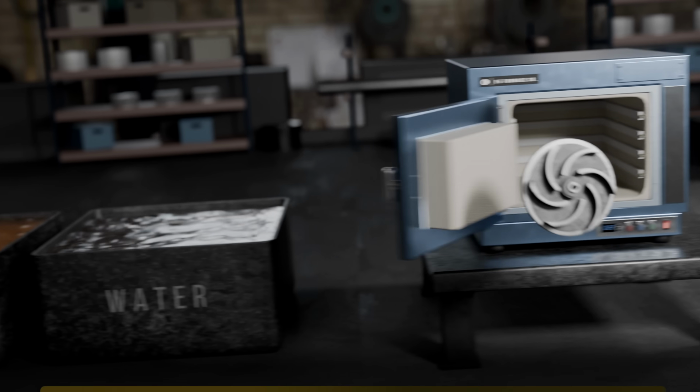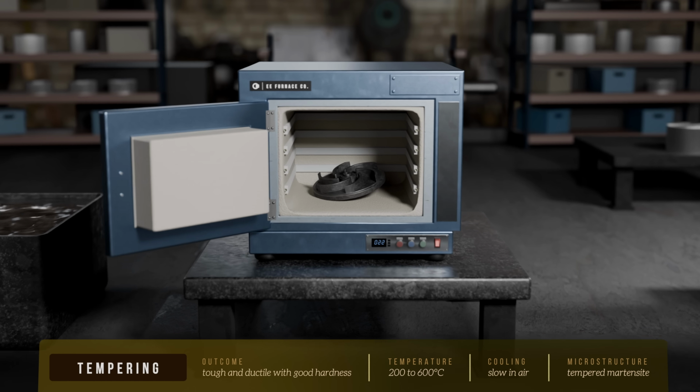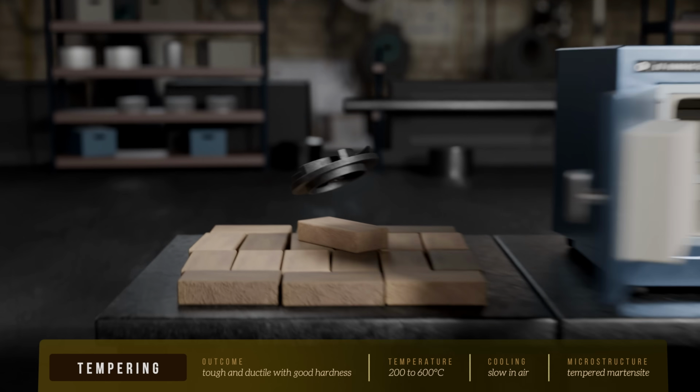Tempering is a follow-up process to quenching. The quenched martensite steel is reheated to temperatures between 200 and 600 degrees Celsius, below the levels needed to transform the steel into austenite. It's held at this constant temperature for a defined time period, anywhere from a few minutes to several hours before cooling, usually in air.